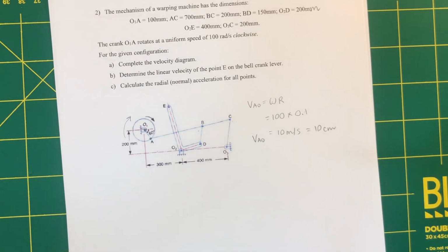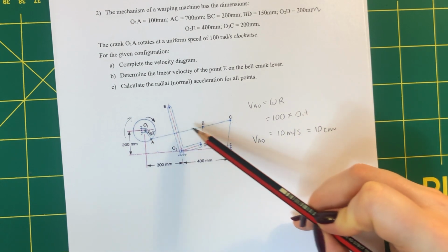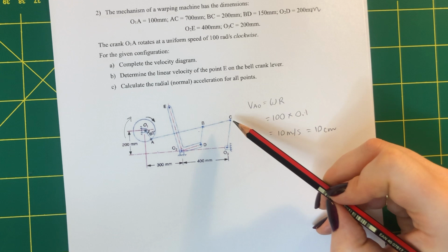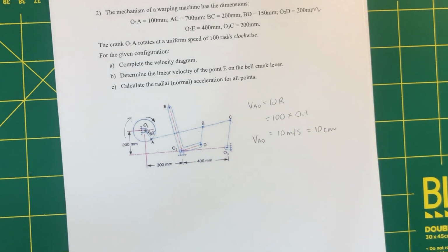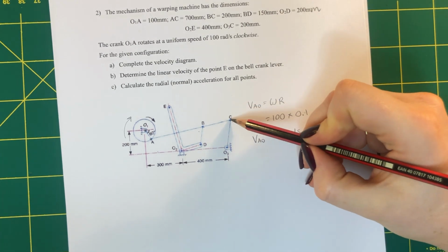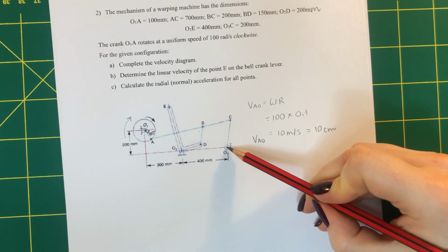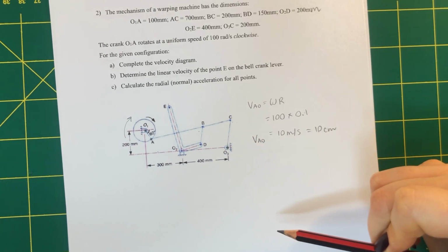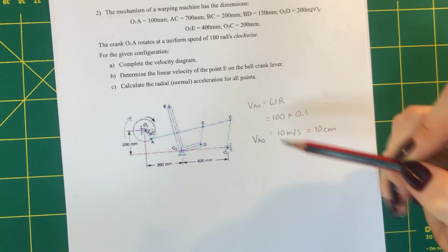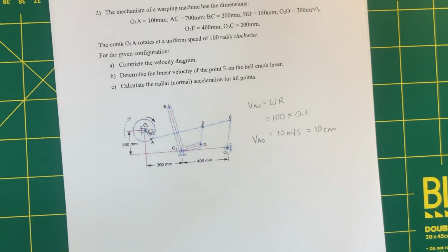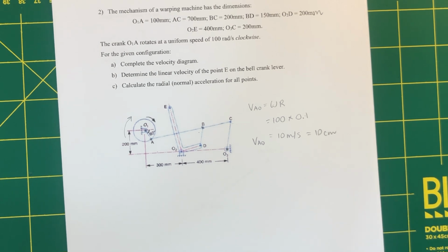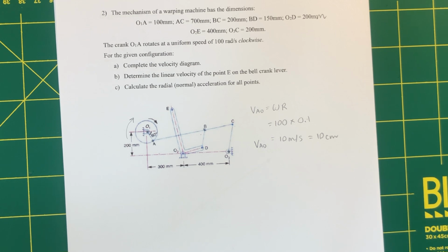Back to our mechanism. We have point A that's connected to point B and point C because they're on the same link. Our next point that we're going to solve for is actually point C. This is because C is connected to a fixed point, O3, so this will make it easier to solve. If you choose point B, you'll have to draw about 4 lines until you find that point. If we choose point C, just like before, we only need to draw 2 lines in. So we're choosing the next easiest point to solve.